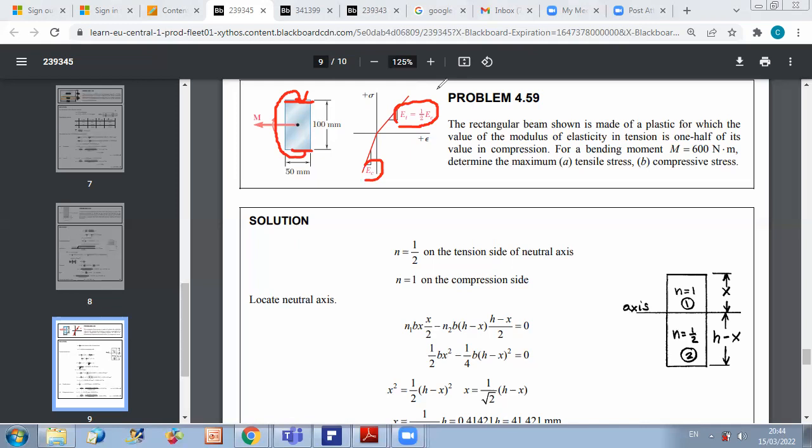This is why we were able to treat before, if we have one material, we treat it normally, we have a linear variation. Here, this material has specific properties. Its elasticity is different in tension and compression. And this is why we can treat it as different materials. And we can consider that the part sustaining compression is different than the part sustaining tension. And then the methodology of thinking is equivalent to the one with different materials, okay?